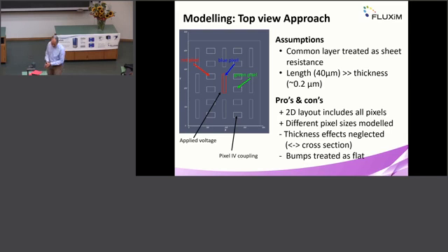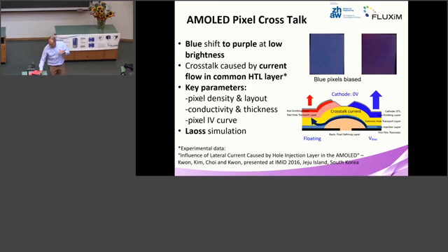And so we have made the assumption that we just used sheet resistance for the common layers. Instead of doing a 3-dimensional simulation, we assumed the common cathode, which can be seen here in the cross section. There is this gray layer, that's the common cathode, which is kept at one potential of 0 volt in this case. It's uniform across, but the other electrode is patterned, right?